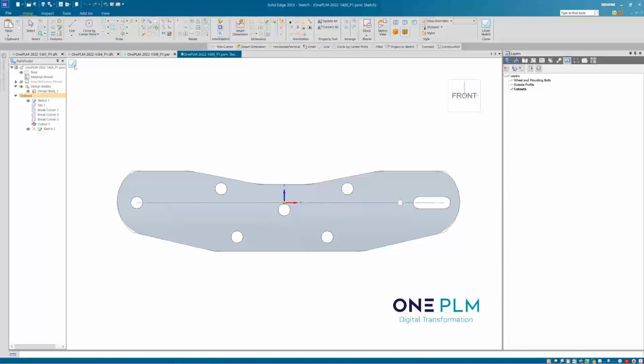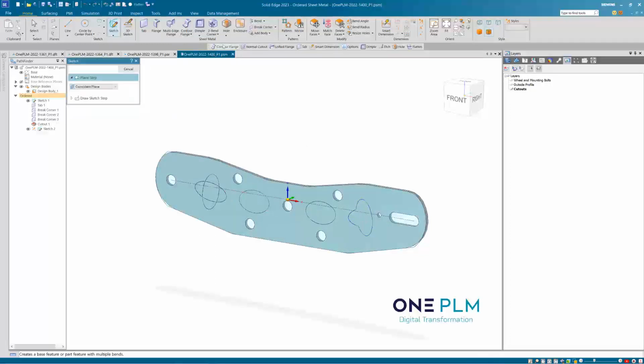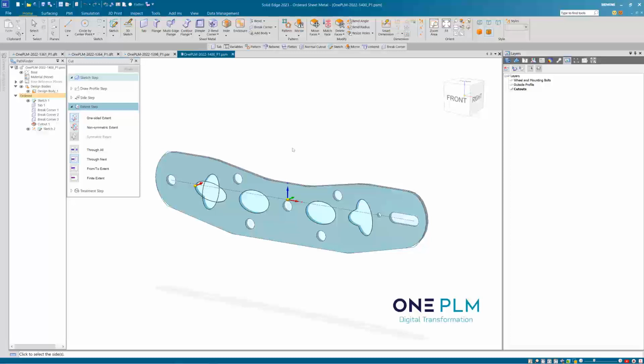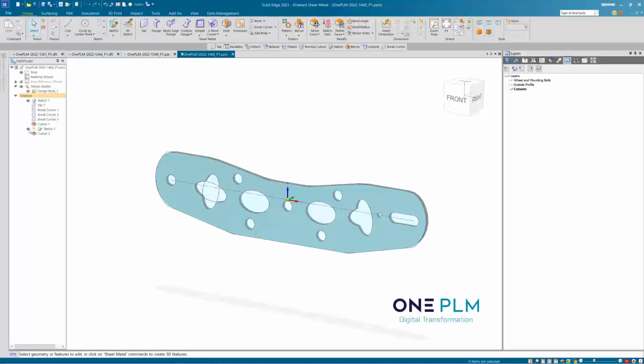Once we've done that, we're going to close our sketch. And then we're going to finish, and then we're going to use our cutout command. And we've got all sorts of different options. So if we go select from sketch, single, we can choose all of the edges, and that's going to select the appropriate regions that are within those edges. Just going to remember the setting from before, so we can choose that as a through option. But we need to remember to turn the sketch off, and then turn those other sketches off on there as well.